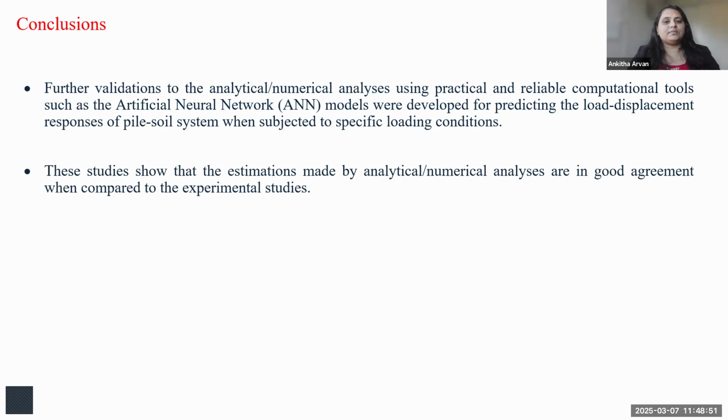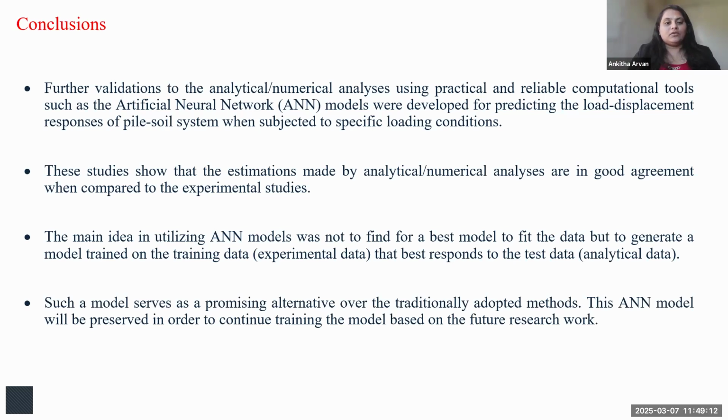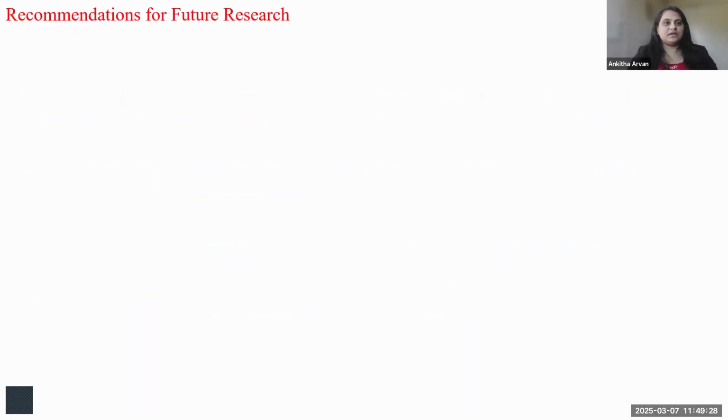Then these studies also showed estimations made by analytical and numerical analysis, which were in good agreement when compared to the experimental studies. The main idea for utilizing ANN was not just to fit the data, but, like I said, to generate a model based on the training data and the one that best corresponds to the test data. And that model serves as a promising alternative over traditionally adopted methods. As we see, it's faster and it's providing better computational time. And it gives an idea of which parameters really affect the displacement responses.